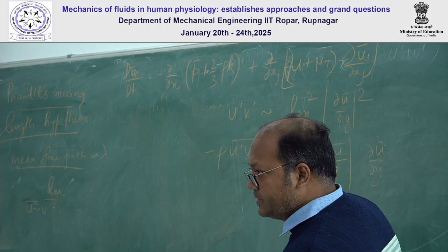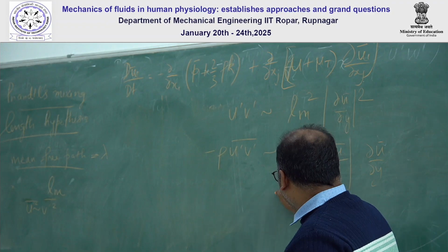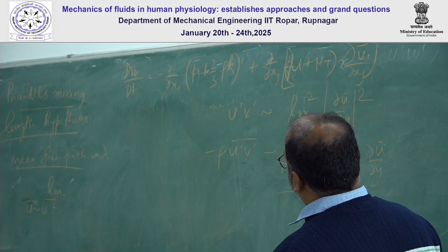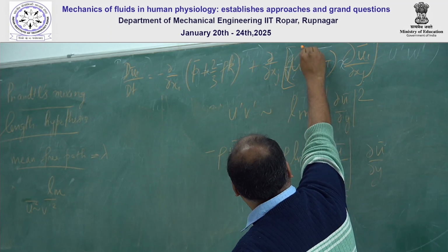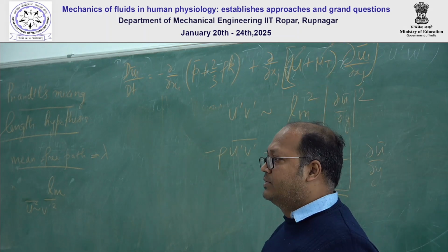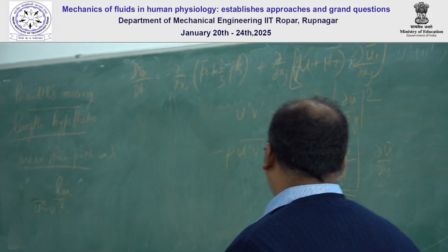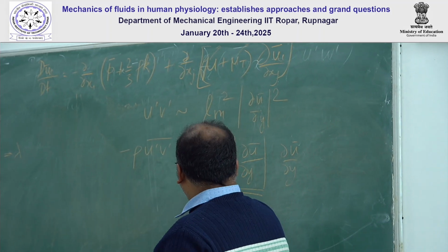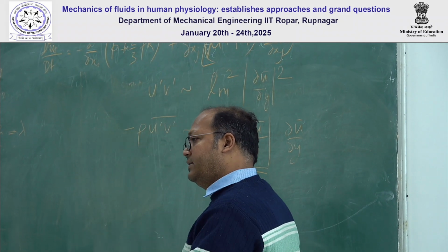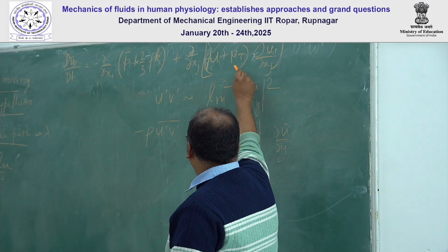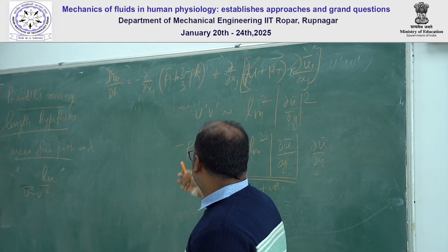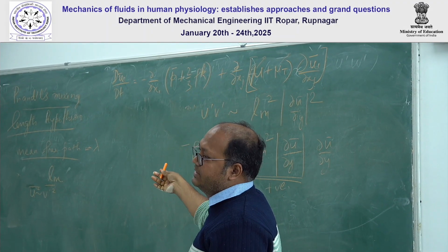So let's not get obsessed with the plus minus sign here. We have done this to keep this quantity at least a positive quantity. Since viscosity is a material property, it is a positive quantity. So ideally the turbulent viscosity we are trying to take as a positive quantity, because we know that the dissipation is higher in the case of turbulent conditions. That's why mu t is aligning physically, that we have to make it positive. It never happens that the friction is decreasing in turbulence, right?